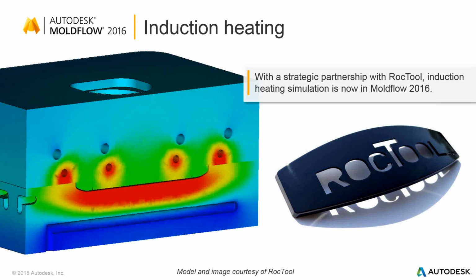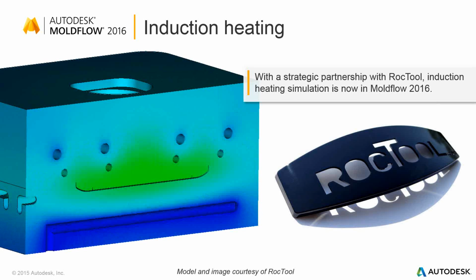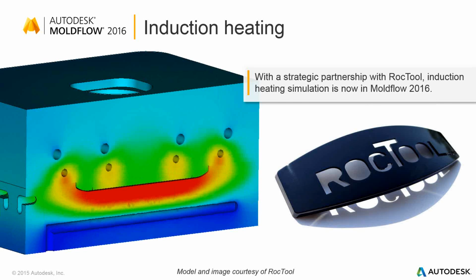Just phenomenal. Particularly in combination with processes like MuCell or other foaming technologies, the Rocktool induction heating technology can still create a high class A surface finish even with foaming technology being applied. So very interesting technology, and certainly something that's unique to Moldflow right now, and a technology that we will probably see a lot more of in the next couple of years.